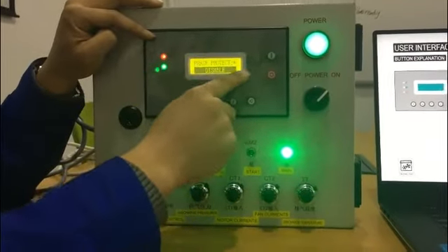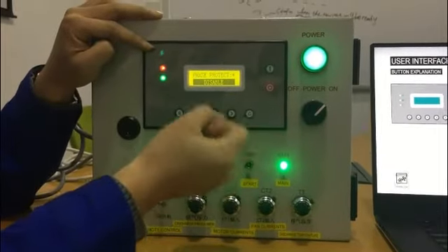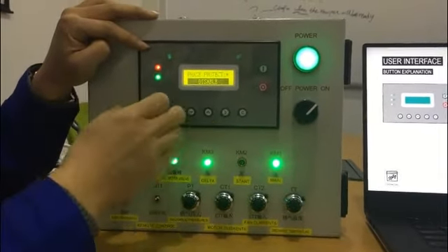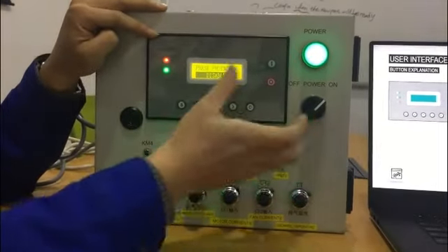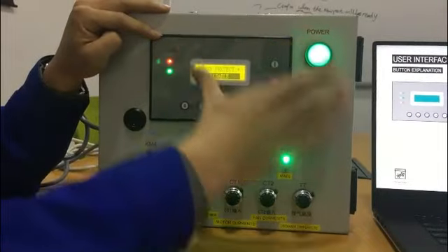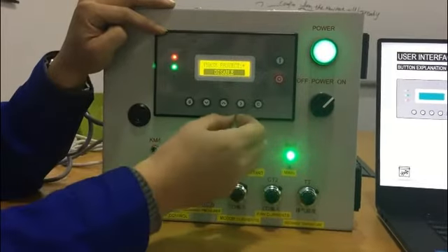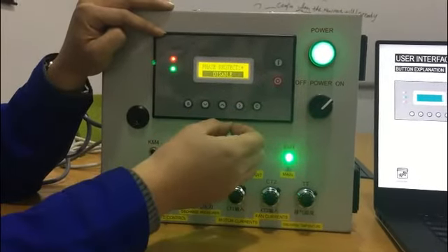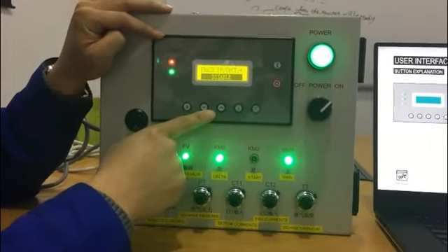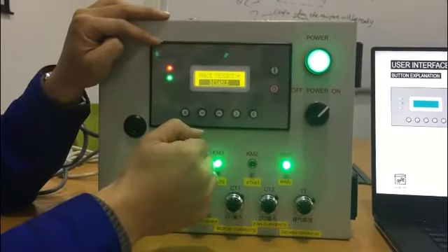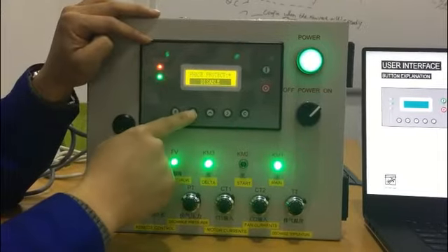Of course, we have phase protection. That means if you connect the supply phase sequence to the controller in a different way, the compressor cannot run, and it will display the phase result on the screen, and it cannot run until you solve the problem. Because this simulator is single phase, I disabled this function.